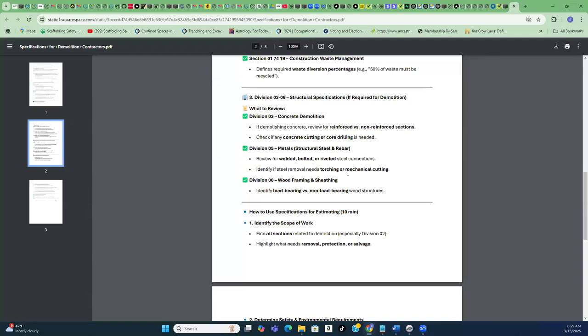Now if you're doing the MEPs, mechanical, electrical, plumbing: plumbing's Division 22, HVAC's Division 23, and electrical's Division 26. A lot of GCs want you to demo the MEPs too, but you got to know what you're doing when it comes to that. So you've got to review everything in the specifications that's related to everything that you are demoing.